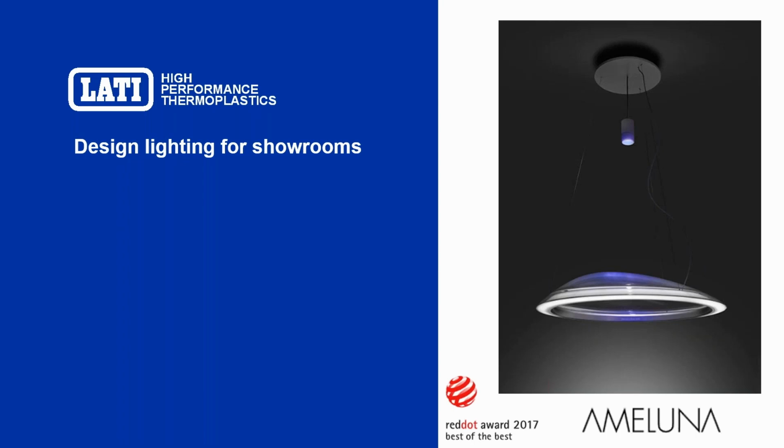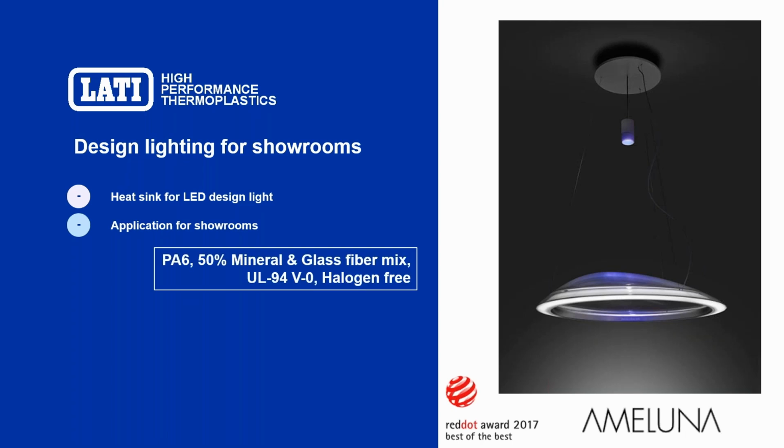This other case history is about design lighting for a showroom of a very important automotive brand. This component, made with our LATI conductor, was the heat sink for the LED light. It was a polyamide 6 with 50% mineral filler and halogen-free flame retardant.